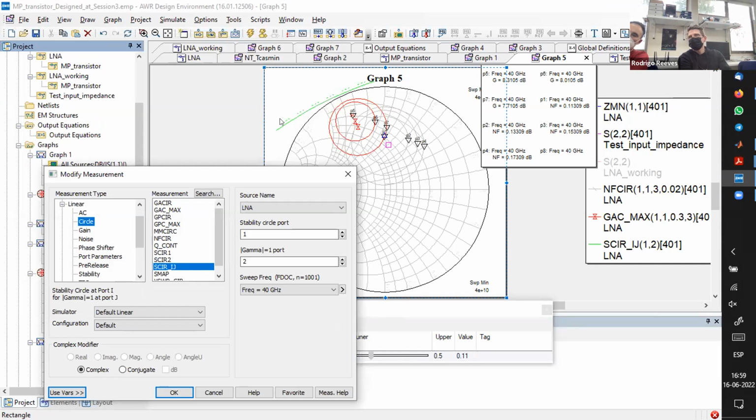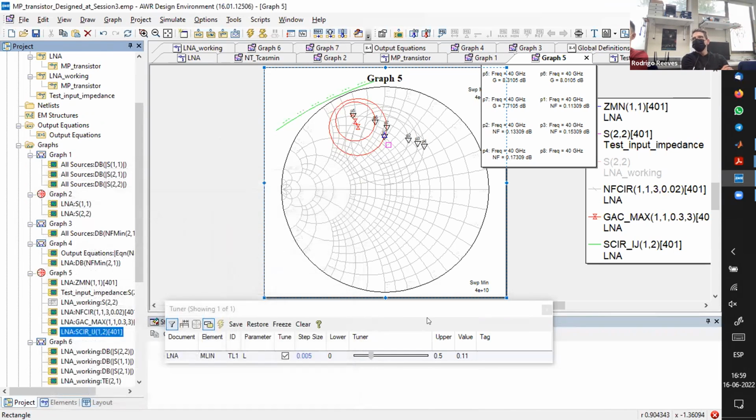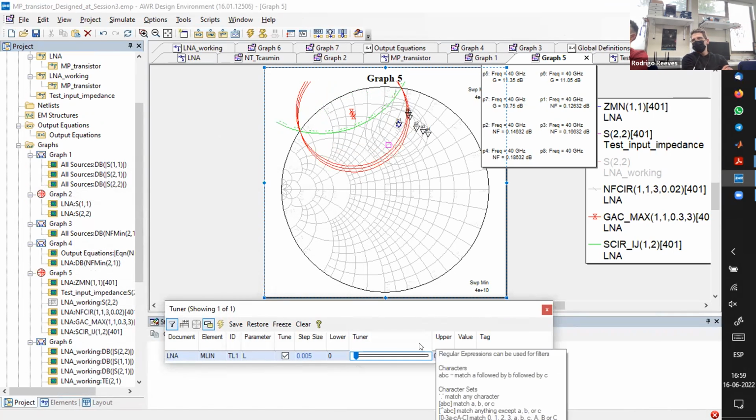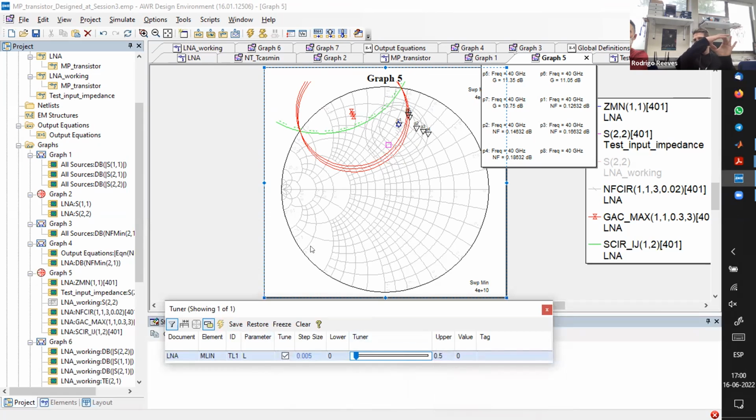Well, I think that this is the gray. Or does it show it there? Yeah, those are the points. Okay. If you reduce the feedback, I think you will get in. Okay, I put this at 0. The fact that those are like points on the top side is showing where it is shaded. It's unstable. So now inside the green circle is the unstable region. So if you would match the transistor with that impedance, it would oscillate.